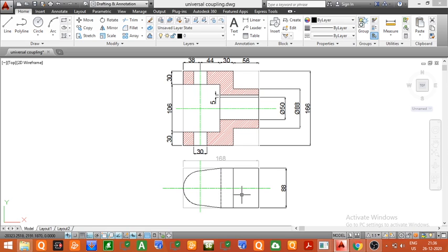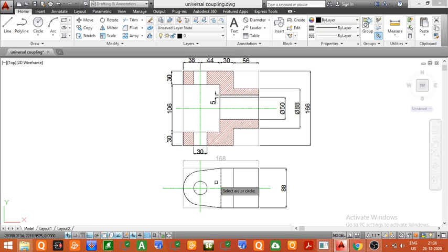Now in the next step, we have to draw the top view of the holes. Now you can see we have this hole. This hole, if observed from the top view, will be clearly visible because this is a hole. If you observe from the top view, this hole which is of diameter 30 mm will be visible. So for a hole we have to draw a dark circle of diameter 30 mm, since it is visible. So now we are drawing a circle of diameter 30 mm. So this circle is of diameter 30 mm. You can check here. I will give you a dimension.